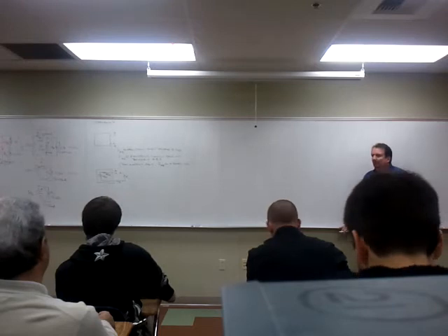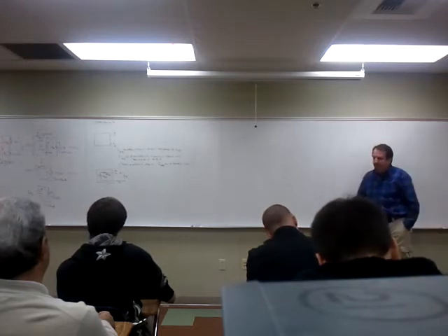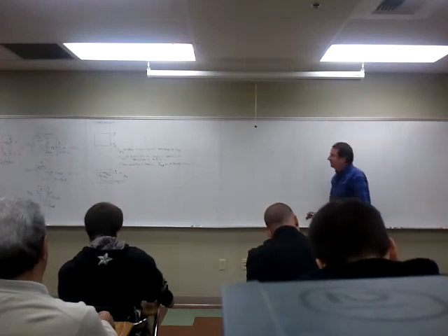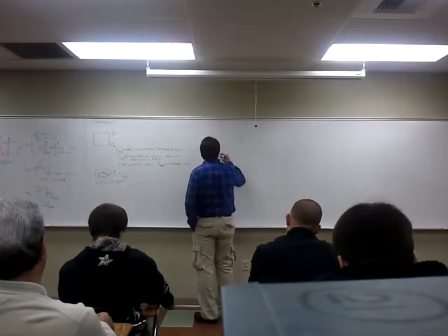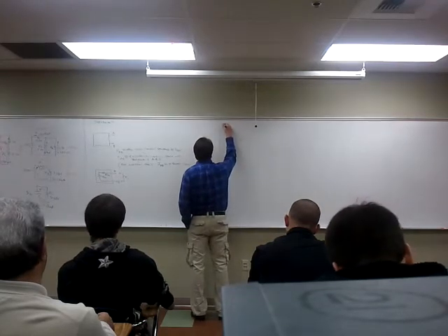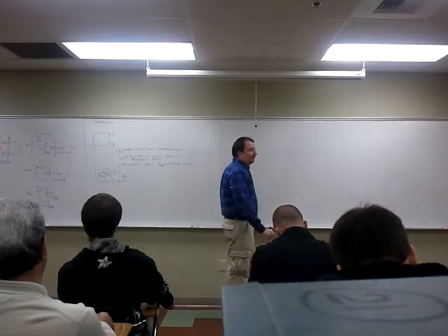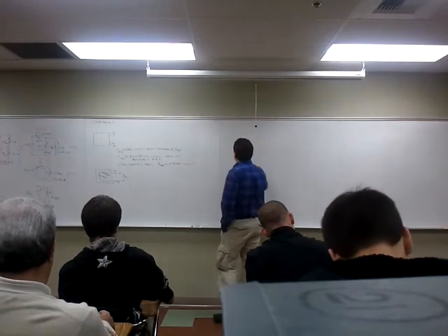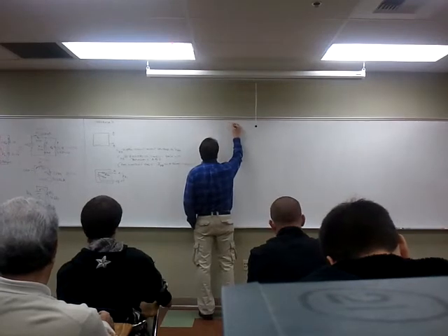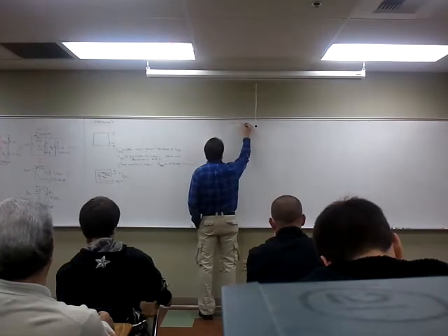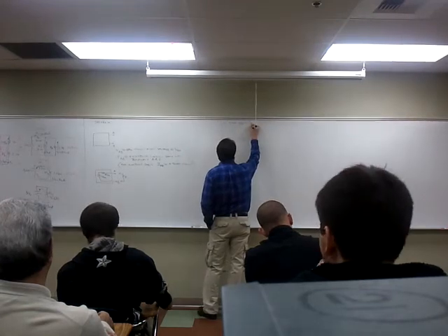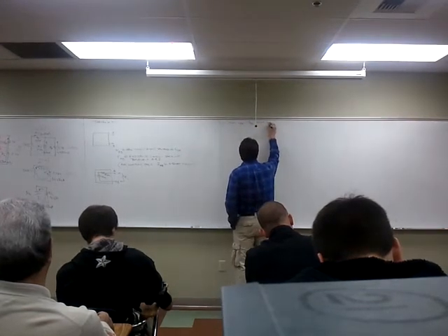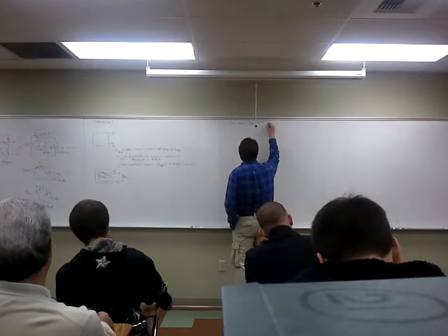But to see more about what this really means, I've got to solve this for Thevenin's first, because it doesn't mean much until I show how to solve for Thevenin's. So to do Thevenin's, it doesn't matter the order. You can find V Thevenin, you can find R Thevenin. What I'm going to do is find V Thevenin, which is equal to the voltage between A and B with RL removed.